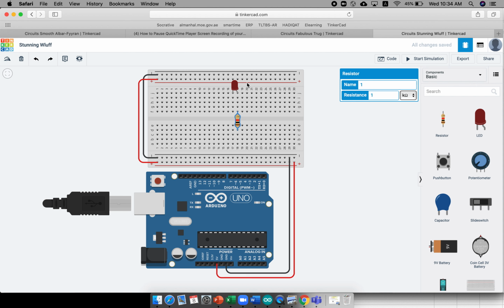Let's assume the first LED here, I want it red. Click on the LED and take green. Let's change to green. Now assume that I will be using the pins 6, 7, 8 for 3 LEDs. Taking pin number 6, we said here is okay, here or here. Both will work. And I don't have to add a wire here. It's pointless because inside the breadboard, these are connected.